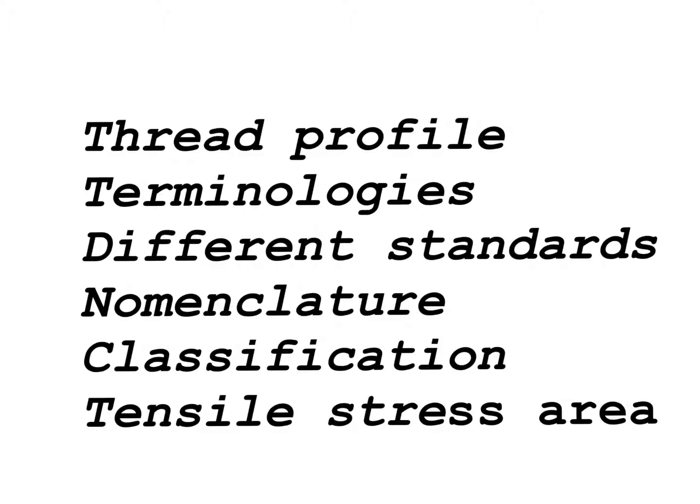Then in that particular video we talked about the classification of thread profiles like the fine thread, the coarse thread, the multiple start threads, single start threads, and what is its implication on the lead of a particular screw thread. Towards the end of that video, we also saw the concept of tensile stress area and how handy it is when you are asked to compute the stresses on bolts.